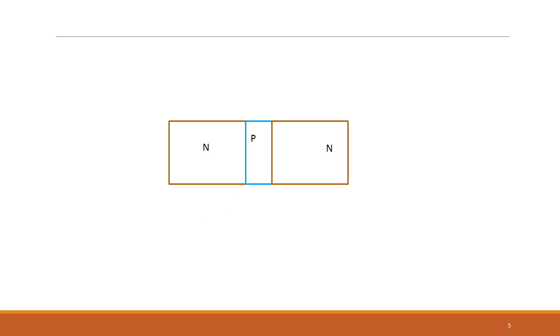Okay. So the E1 without the bias is in this direction with the large one, and E2 is in this direction. Because we are forward biased, the E1 will actually reduce, and then you reverse bias the collector-base junction further, so the field across this increases.